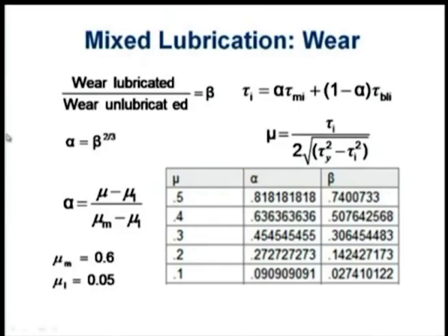Again, as a hypothetical, in that situation, if we substitute the values and figure out alpha, it turns out to be 81.8%, or compared to metal to metal, it is reducing by around 18.1%. So, coefficient alpha is 0.8181 or maybe say 0.82, but beta is lesser. That means having a lubricant has more effect on beta compared to alpha.